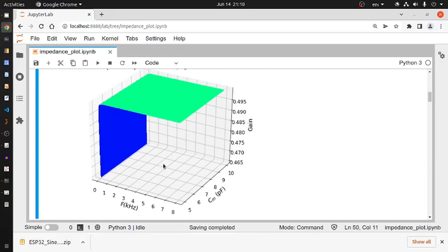Let's say at 6 kilohertz and 7 picofarad capacitance of the mic condenser, it is offering a gain of, let's say, 0.49, correct? If we shift to 7 kilohertz, it is also offering the same gain. That means there are no distortions coming from this biasing circuit, and it is independent of the frequency and the capacitance value, right? So this is interesting.